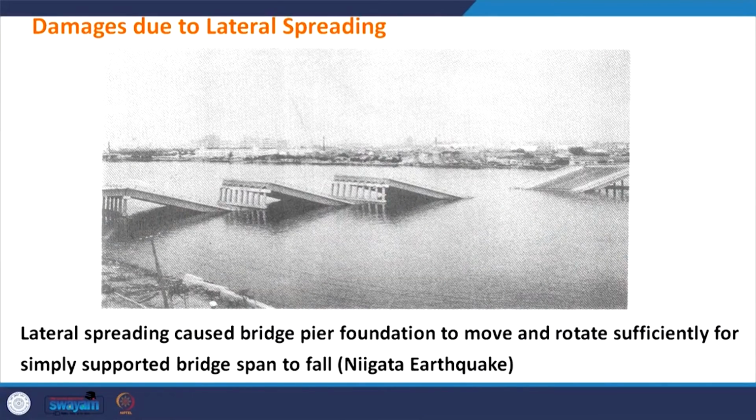Then let us see the example of the foundation of the bridges. This slide is also from the Niigata earthquake, and the bridge got damaged due to lateral spreading. Lateral spreading is a phenomenon related to liquefaction, and you may be aware that during liquefaction, due to shaking of earthquakes, there is an increase in pore water pressure.